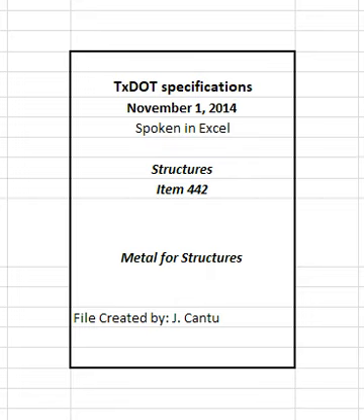The quantity to be paid is the quantity shown in the proposal unless modified by Article 9.2, Plan's quantity measurement. Additional measurements or calculations will be made if adjustments of quantities are required. The maximum percent variance from the plan's quantity will be as given in Table 5. Table 5. Percent variance. Quantity and variance. Quantity over 1 million pounds has a 0.5% variance. Quantity of 100,000 through 1 million pounds has a 1% variance. Quantity under 100,000 pounds has a 1.5% variance.